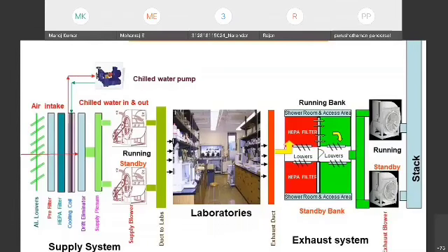So it is not going to be radioactive here, but after the air gets cooled, it becomes hot. Now this air is considered to be active air, radioactive air, and it will be passed through ducts. These are all GA ducts. Here we will have MS ducts or SS ducts, and they will be leak-proof ducts. Through these leak-proof ducts, it will pass through HEPA filter chambers or HEPA filter banks, where we will have a row of HEPA filters, and this active air will pass through them.